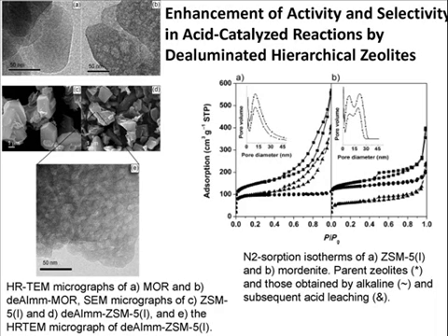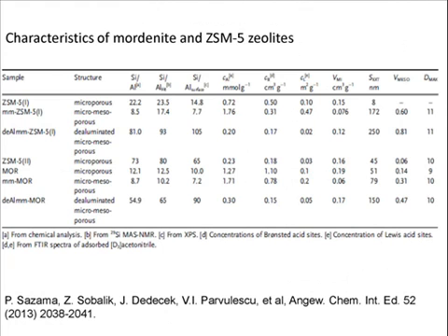And we look here at the characterization of this kind of materials. They are indeed mesoporous, they are indeed dealuminated, so they have all the properties. But the problem was, are we indeed able to do this? And we checked, in our laboratory, two things. One, cracking of n-hexane, which remains a very important reaction. And the other was one reaction which was also investigated for a long time here in this house, the acylation reaction. And we look at acylation of anisole with acetic anhydride.